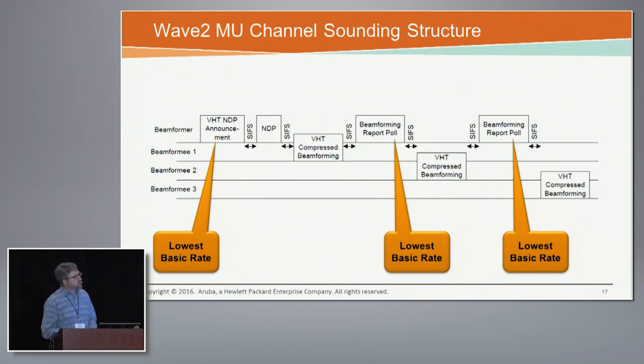Now with Wave 2, of course, before I can do the MU transmission, I have to understand the channel state to all the stations that I'm about to talk to, and that channel state varies on a much more rapid time scale than it does for beamforming.